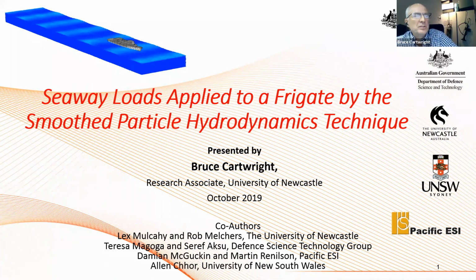But now that we're looking at the flexible ship and we're refining the mesh in areas where we have or hope to model cracks and corrosion, the simulations probably now run out to about 24 hours on probably about 50 or 70 cores. So at the moment, we're trying to keep the model size to be no more than 1 or 2 days with the number of CPUs that we have available.